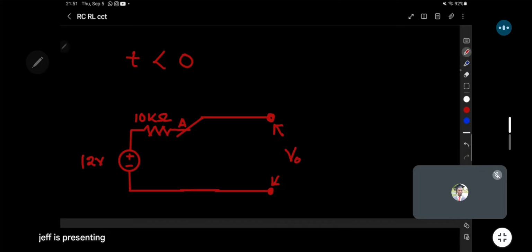Well, with the capacitor behaving as an open circuit, there will be nothing happening to this resistor because current will come like this, and then finds this junction nowhere to go, so the circuit is not complete. So if this was a bulb, it would be off. So because of that, the potential difference that will be measured between these two terminals will actually be equal to what this source is supplying.